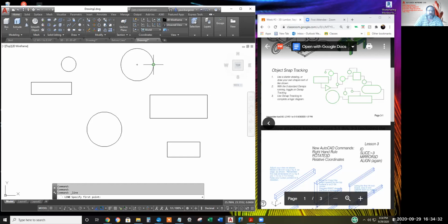Now, usually, the first point you select automatically is acquired. Gently pull your cursor away and you can see it leaves a slight plus sign at the acquired point. In a second, you'll see an invisible straight edge line up with that in accordance with the polar tracking angles.